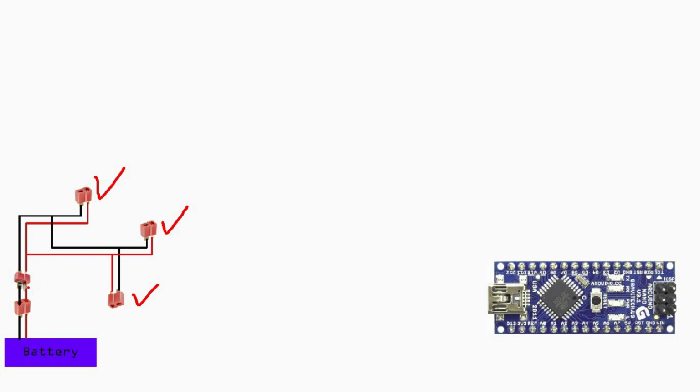As you can see, I connect the battery to a male connector, but on the other side, if I want to make it modular so I can remove various portions, I'm going to use a female connector, because this is the one now supplying the power. It's a good idea not to use the male connector for supplying, so that you don't have something protruding out and accidentally short circuit it. Normally that's what I do: if you are supplying power, female connector; if you are receiving it, use the male one. Now I have three connectors, whereby I can connect to various portions of it.